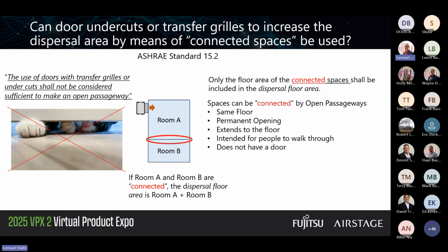Another question we have got for years now, and even now, is: can you use door undercuts or transfer grills? And you cannot. Above that cat picture, that's the wording in the standard. You cannot use transfer grills or undercuts according to standard 15.2.